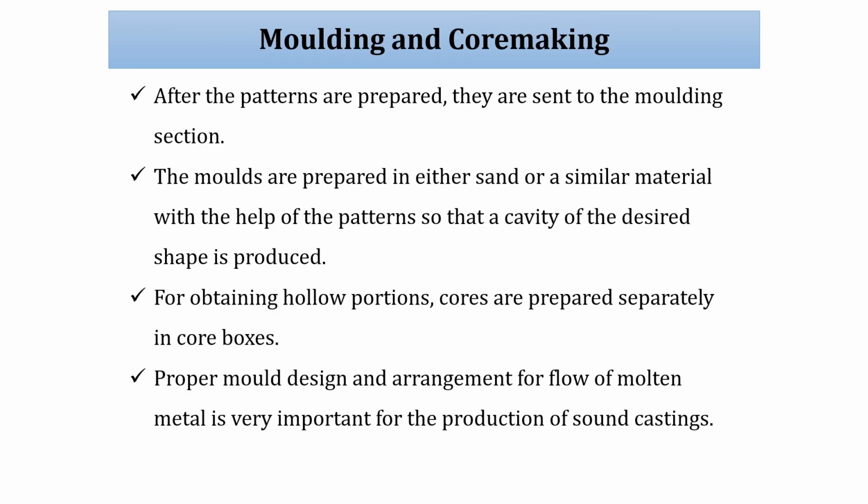Mold making and core making are one section. There is not too much difference. You get the pattern design, and based on that you design your molding and core making process. If there is no hole, no hollow product, there is no core making. If there is a hollow product, you have to provide a core. These are just a brief understanding. Chapter-wise, we will go into details: what is fettling, why it happens, what is casting, what is solidification, and what is molding.